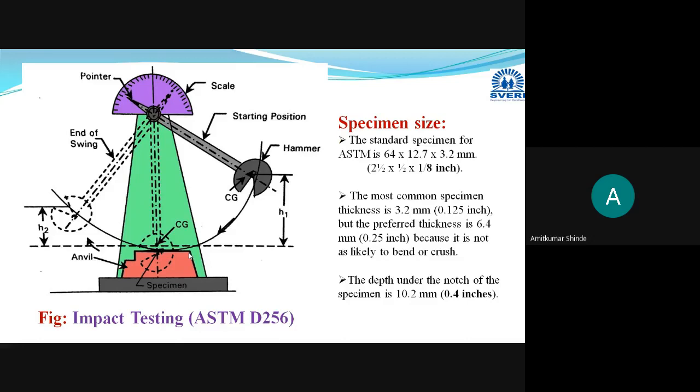For conducting the IZOD impact test, the standard specimen is prepared with the mentioned dimensions according to the ASTM standards, that is ASTM D256. According to these standards, you have to do the test specimen preparation and follow the particular test procedure.